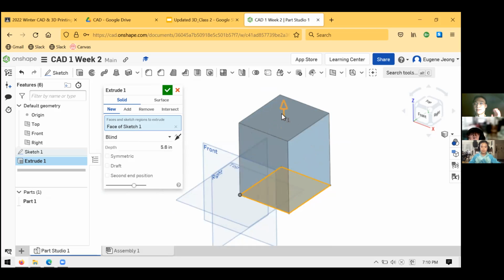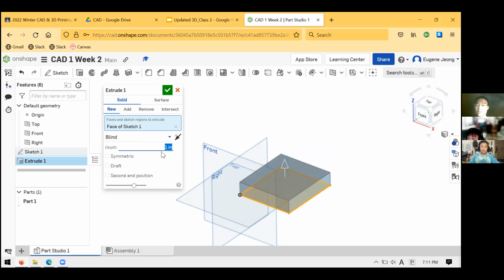And that gives you an idea of how we're working. Almost all of our work happens in these two-dimensional sketches, and yet we use these to create 3D objects. So to be more specific, maybe you don't have to worry too much about this right now, but you can specify a depth. And that just means how far you should push the material out to create this object. So maybe I'll just say 1 inch. This doesn't really mean anything right now because I didn't dimension my original sketch, but I'll go back and cover that in a second.